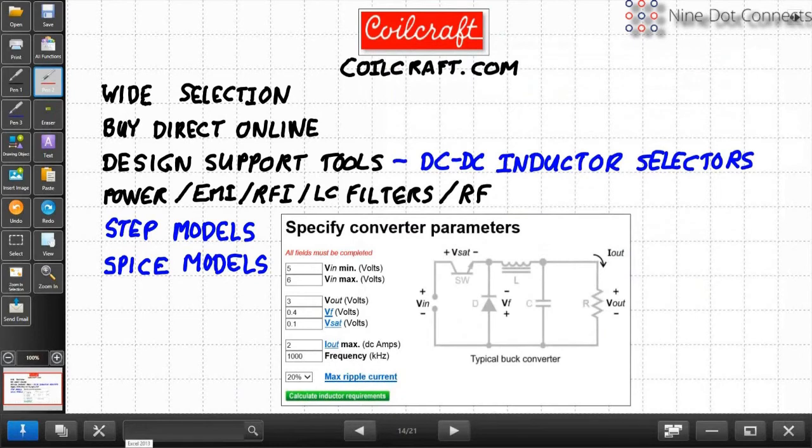Okay, so let's back away from this for a second. How are inductors shielded? That's a question somebody asked. Typically, in inductors we're talking about magnetic shielding. They can also have electrical shielding, but usually that's not the problem. Usually it's the magnetic flux coming out of them. If the magnetic material completely encloses the device, such that there's no open place where the wires can be seen, say it goes through a pot core, or there are two pots together, then it is magnetically shielded. That can also form an electric shield.